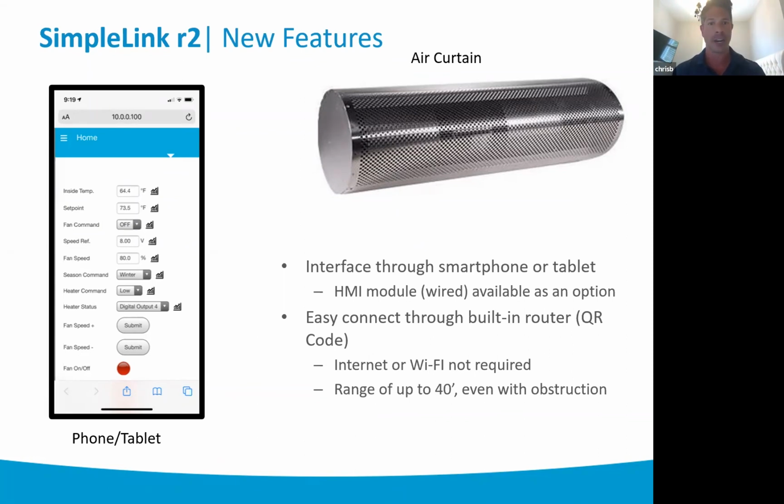It's going to make that air curtain intuitive, meaning it's going to ramp that airspeed up and down, depending on what's needed, depending on that temperature delta, depending on that pressure delta that I talked about earlier. There's also preset modes in there. For an example, one of our modes, when you first set that up, is going to look at door operation.